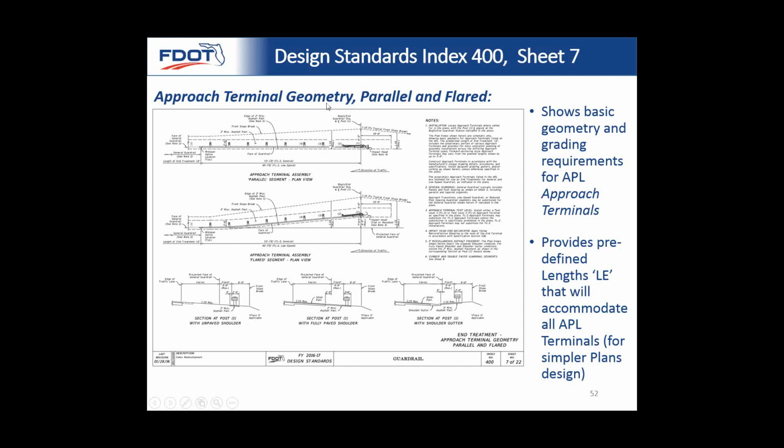If that's on the approach side, where head-on traffic is going to hit this thing head-on, you want to avoid the W-beam spearing through the vehicle. That's what these are designed for. In some cases they extrude the guardrail or redirect it away from the vehicle so it doesn't spear into it, and they absorb a little bit of energy before you get to the more rigid portion, to be safer for the vehicle. These are designed for head-on collisions, as opposed to the trailing anchorage, which is only designed for the trailing side. The other thing these do is develop a little bit of ribbon strength, so you start having the redirective capability at post 3. It's tied down a little bit to start giving you some guardrail rigidity.